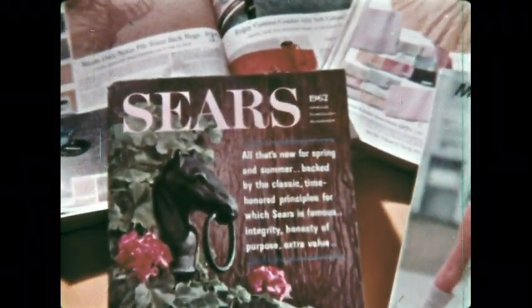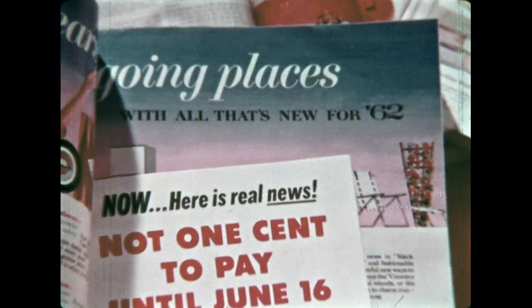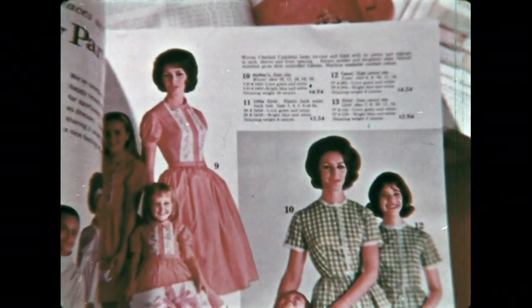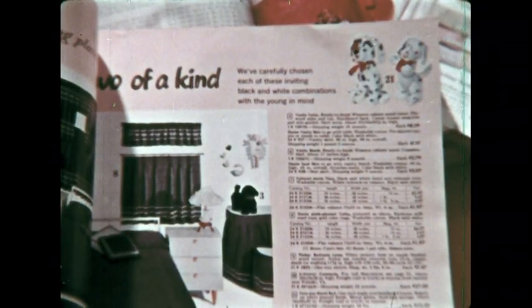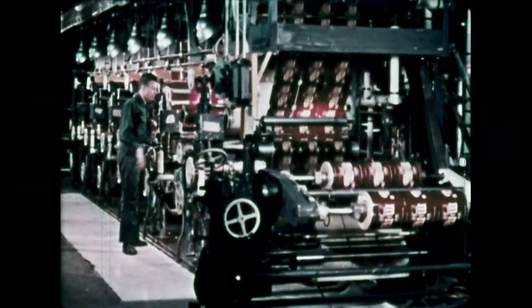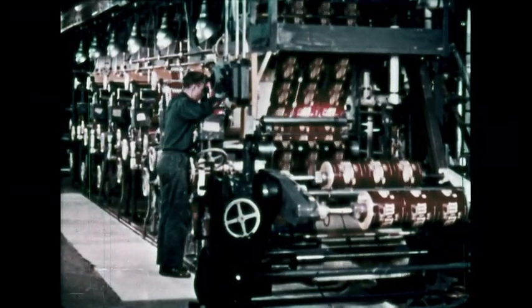In terms of results, intaglio is excellent for printing on paper or cloth, particularly if it is a large volume job and there are many illustrations. This kind of work is generally done by the rotogravure method. The higher cost of making the printing images is absorbed by the large volume they can produce, as well as the lower cost papers they can use. Inasmuch as factors such as these are usually taken into account in selecting a process, they also serve as reliable guides in determining which process was used for a particular job.